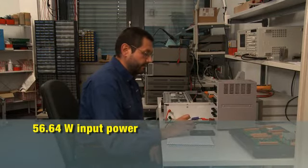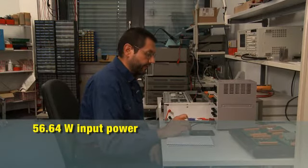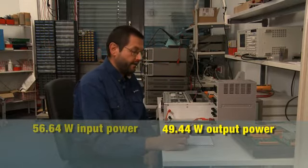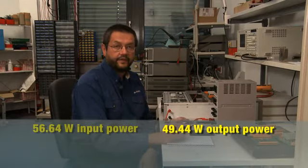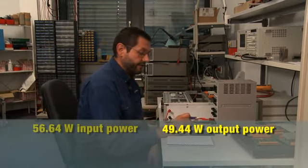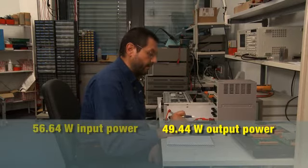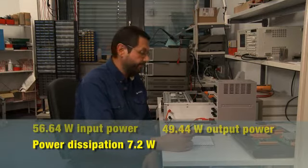The output power as well can be obtained by multiplying the output voltage by the output current. So we have 24 volt multiplied by 2.06 amps gives us 49.44 watt. The difference between the input power and the output power gives us the power dissipated, which is the power that eventually will be converted into heat. So we have 56.64 minus 49.44 gives us a power dissipation of 7.2 watt.